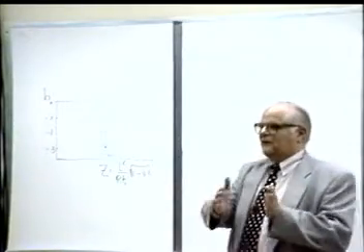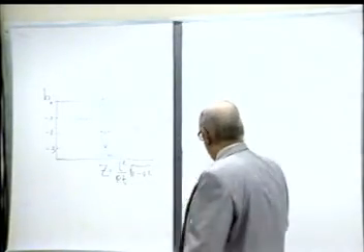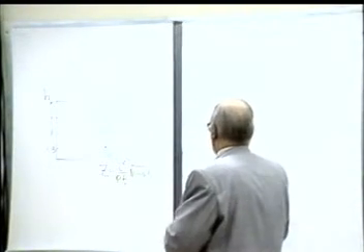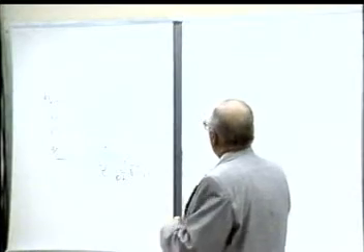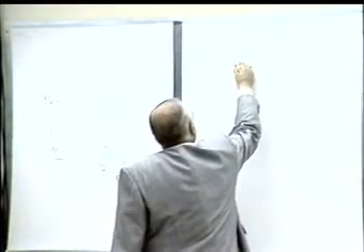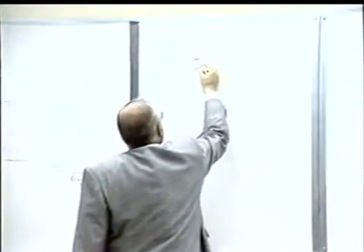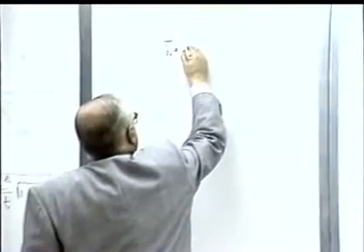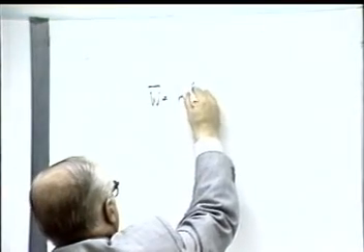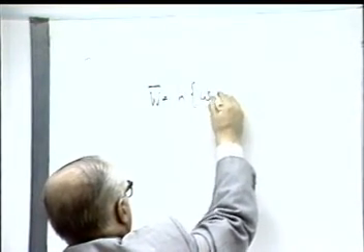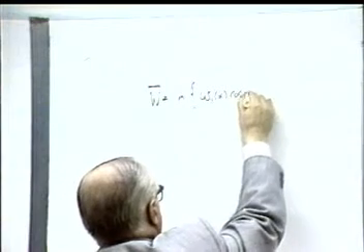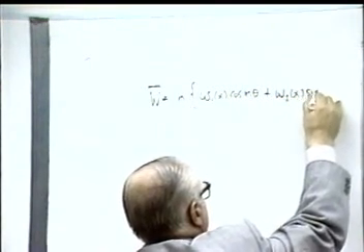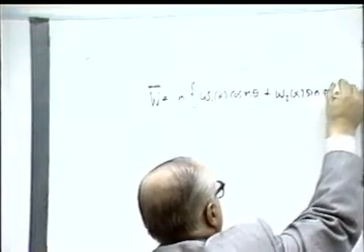You see, what I do in this NASA paper, which I just finished, I look at two types of imperfections. I mean, W bar, I write it, let us say, model 1 is wall thickness times W1 of x cosine n theta, W2 of x sine n theta.